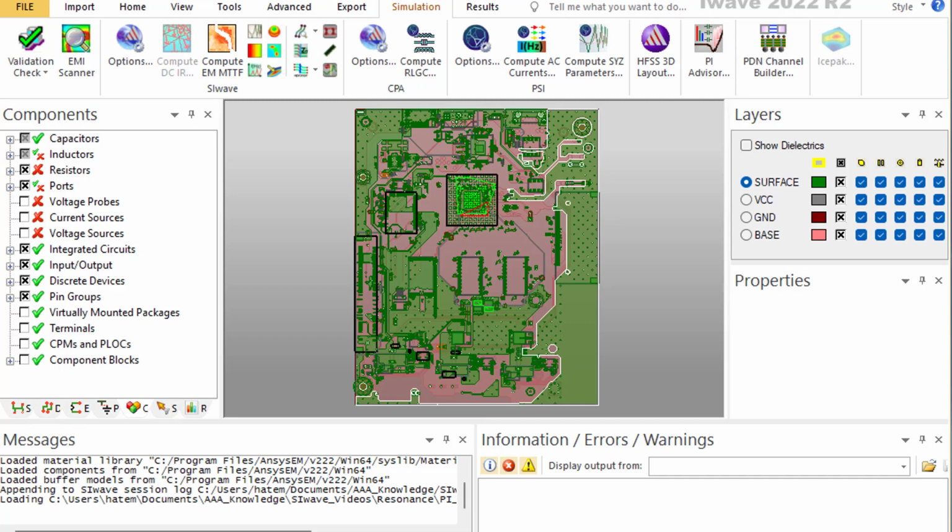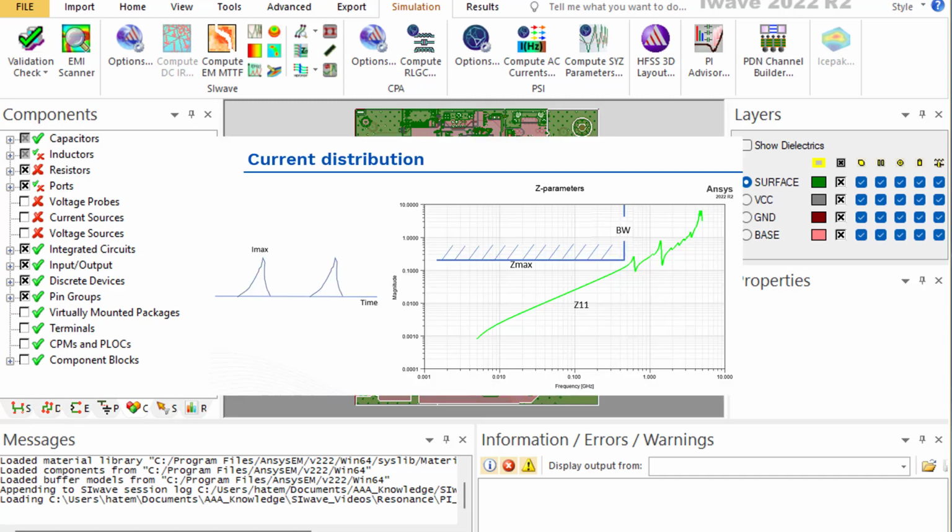The size of the power plane is determined by the expected maximum current and the allowed maximum voltage drop. However, even the best design doesn't have enough capacitance to keep the impedance at low values for a broadband spectrum. The spectrum of the power plane is derived from the current pulses. Power planes need decoupling caps to extend their bandwidth beyond.